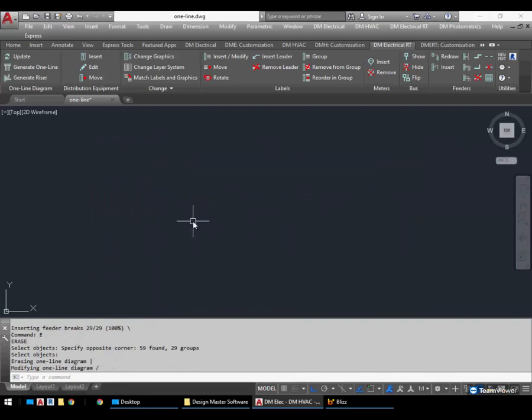We also do a lot of, and we'll do this here, where we generate and then we erase everything and then we generate again. We're going to be doing that because it's convenient for my examples. But in general, when you're doing your work on your project, that's not really the expected workflow either. The idea is that you generate it and you work from there and you slowly massage it into place, and you leave everything where it is without redoing it, because as you add labels and other things, if you keep redoing the generation, you're losing all that other work you've done. You always can, of course, erase and regenerate, but that's not actually the intended workflow for the one-line diagrams. So just keep that in mind as you're working.